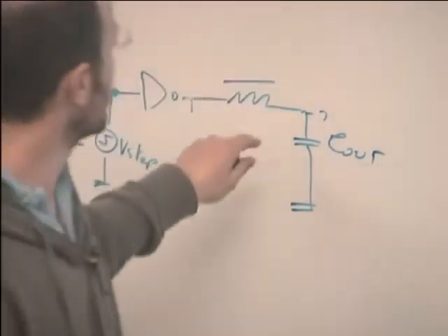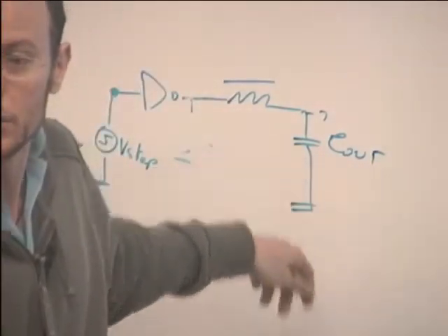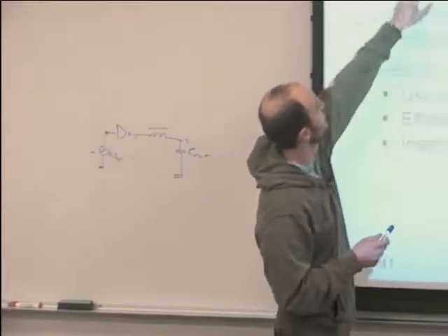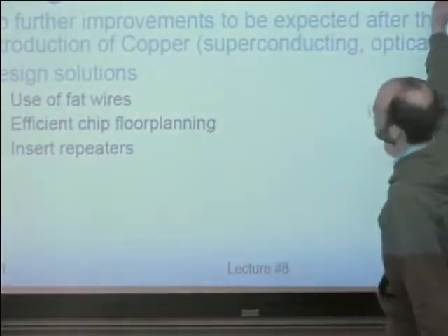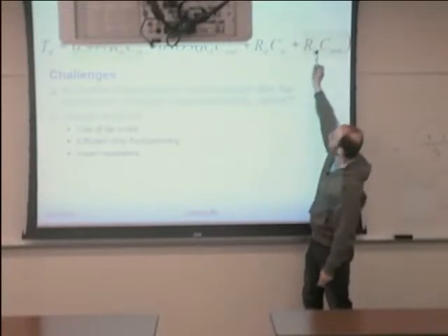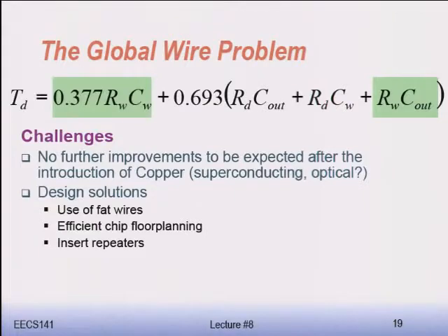The wire will still have its own delay, which is this part plus this part. So now, if you look carefully, this part here especially, and also this part, once you fixed the sheet resistance of the layer and you fixed the distance that you're going, this number you can make smaller by making the wire wider, because you are reducing R wire and keeping C out constant.